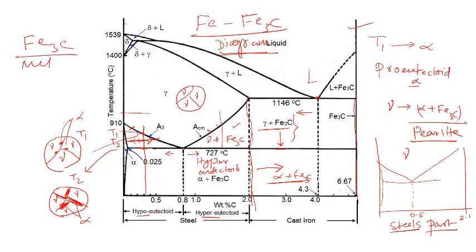We could say that it is something between stable and not stable, a condition known as metastable, something in between. Given enough time and chance, this phase would tend to dissociate into its components, that is iron and carbon. So free carbon would come out from it and iron will go back to the parent material.